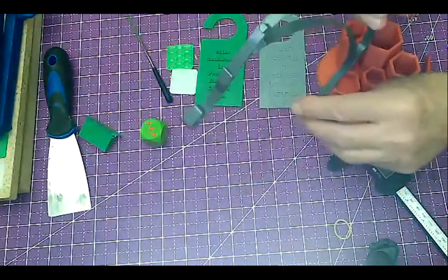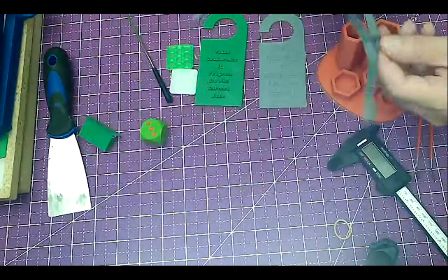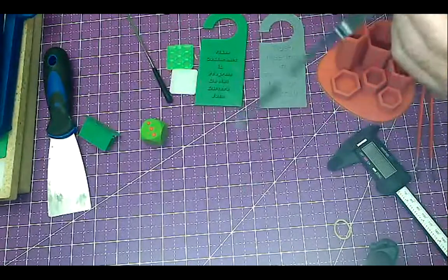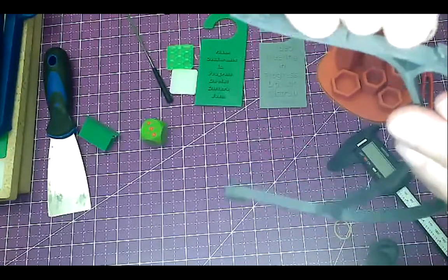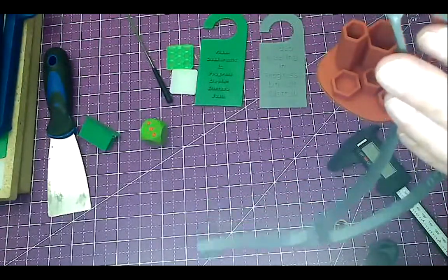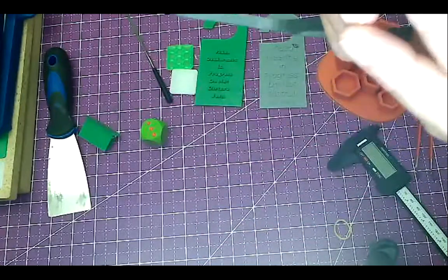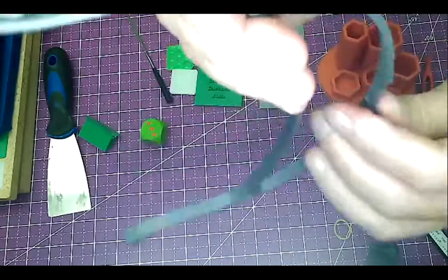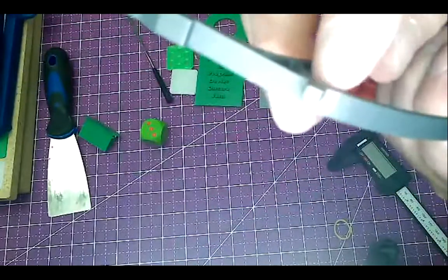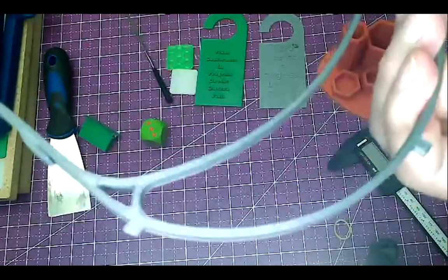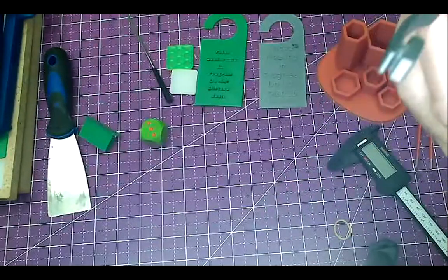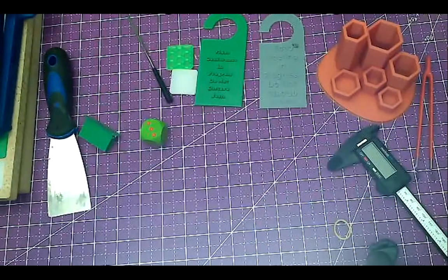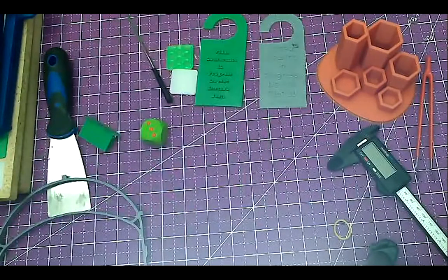And so here's our shield, and oftentimes we'll have to take some of the support material off of it. Like this part right here, this would be some of the support material. Now I realize I don't have it on there. As I look at this, I should have orientated it with this side flat, because that way I wouldn't have these little divots of support material, just little 1, 2, 3 kind of things.